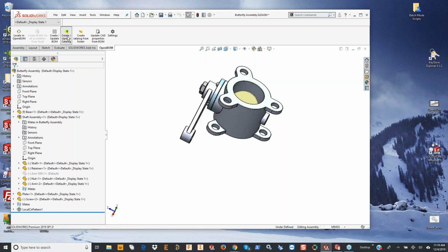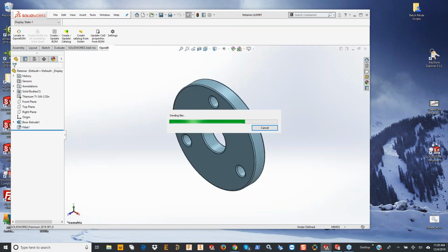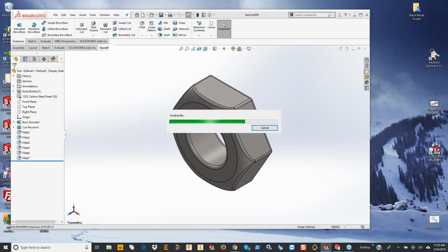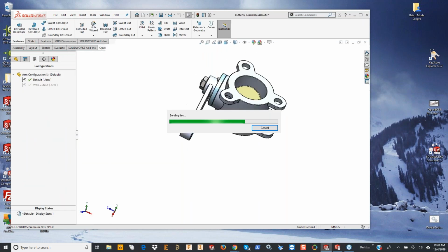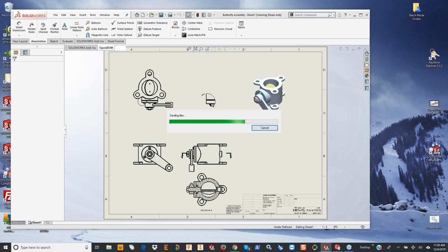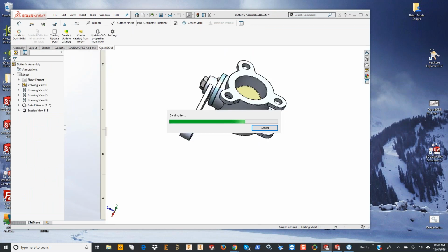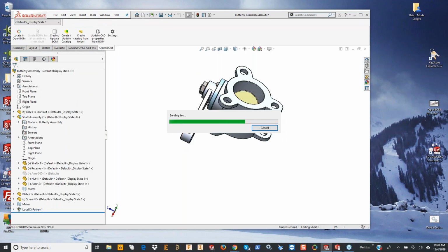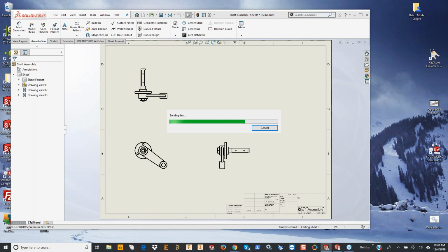And I'm going to create a catalog. I'm going to do this in real time. There's a little bit of time involved. The OpenBOM add-in that you see up there at the top, the OpenBOM menu, is going to go through and analyze the SolidWorks assembly, open each one of the parts, extract any properties that are defined in there, create a PDF of the solid model.